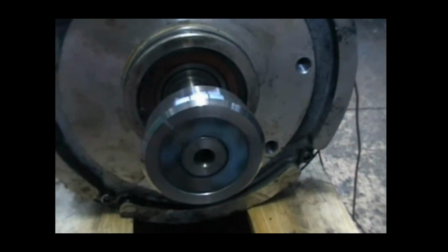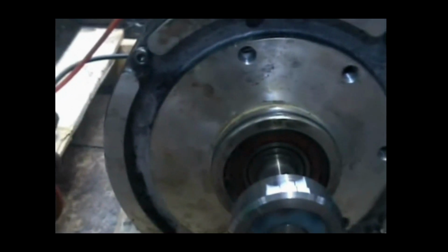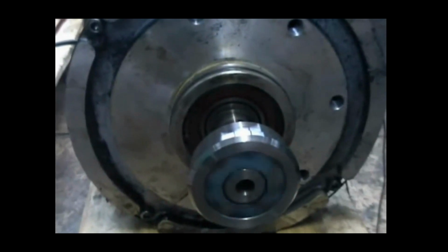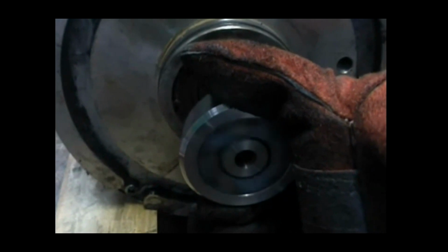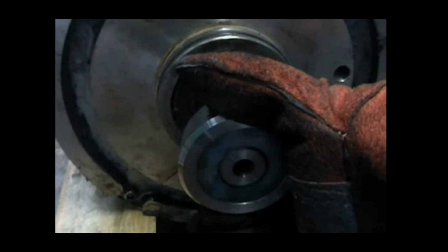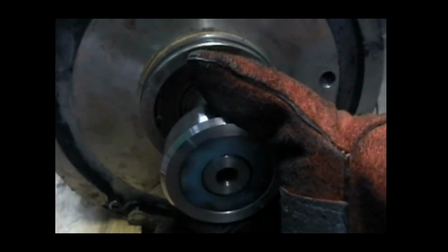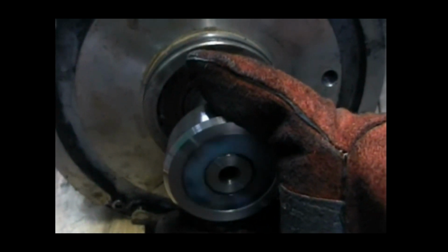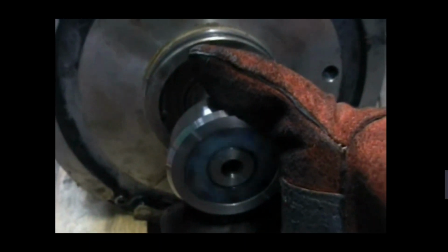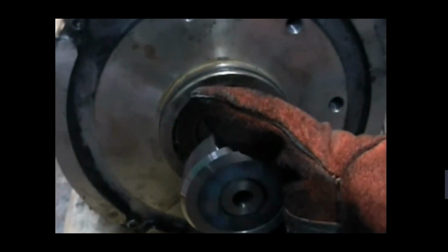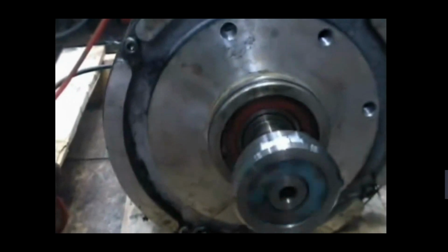Now, as we can see here, the shaft speed has just dropped appreciably. Now the characteristics have changed. That is, when I apply a load to this motor, it tends to maintain its speed, because now it is behaving partly as a shunt machine. And a shunt machine, I'm squeezing the hell out of that now, and I can't stop it.